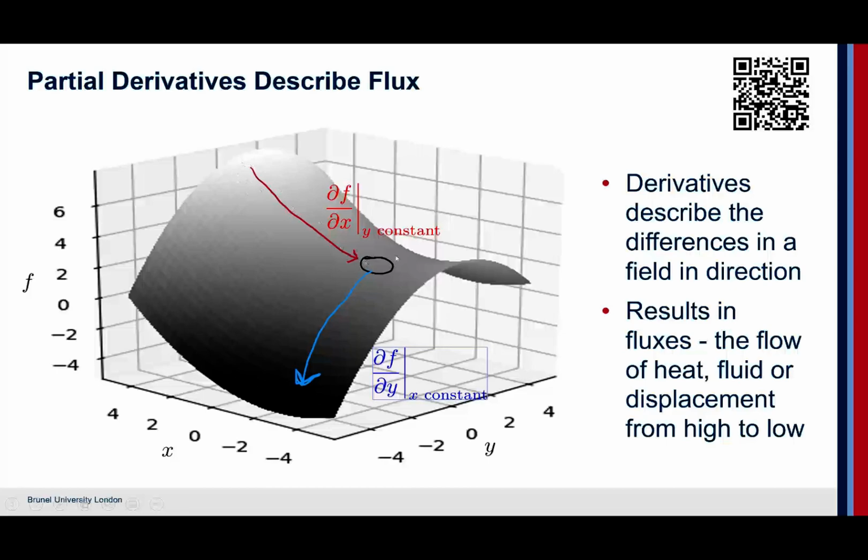So things will move basically to the lowest point if they're moving in x, and then in y they'll move, obviously much faster if there's a bigger gradient. So the 2-dimensional diffusion equation is essentially describing, at the same time, movement in those 2 different directions, and those coefficients kx and ky define essentially how much it will flow in a particular direction. So when you come to physically interpret those, if you double one, you'd expect that flow maybe to be less pronounced in a given direction.